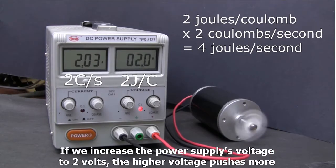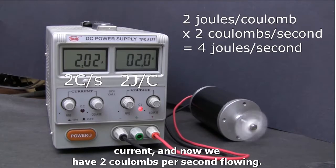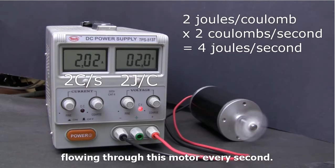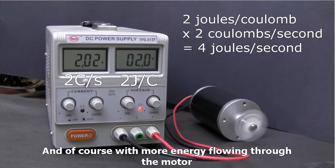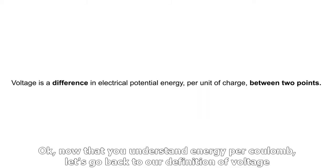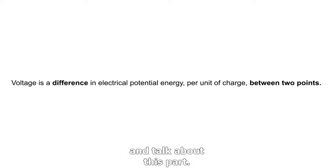If we increase the power supply's voltage to 2 volts, the higher voltage pushes more current, and now we have 2 coulombs per second flowing. 2 volts multiplied by 2 amps means that 4 joules of energy are flowing through this motor every second. And of course, with more energy flowing through the motor every second, obviously the motor is going to do more work and spin faster. Okay, now that you understand energy per coulomb, let's go back to our definition of voltage and talk about this part.